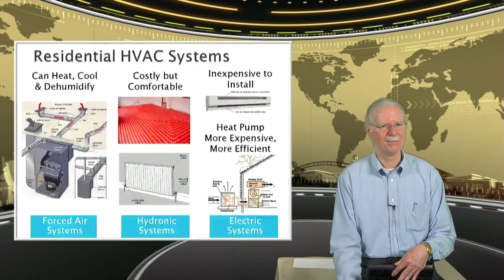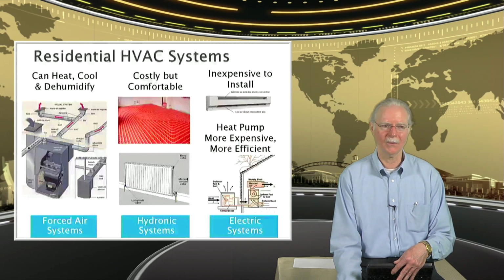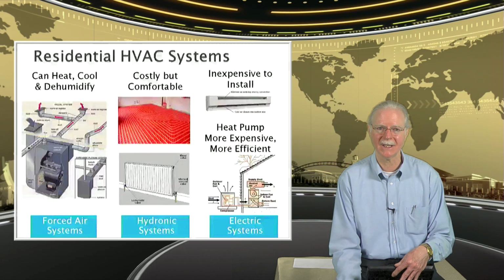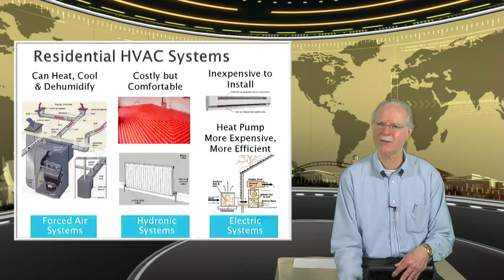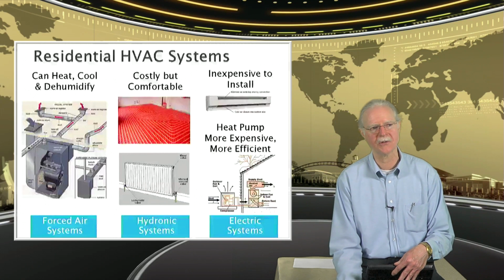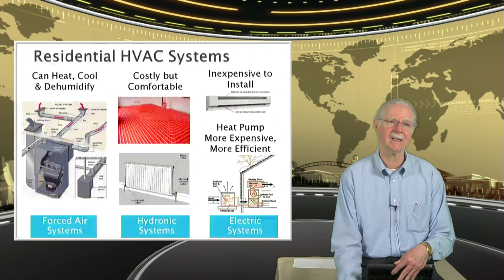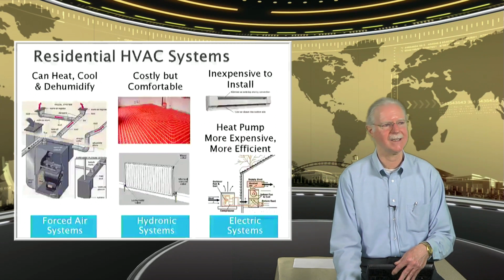Because we're now burning that fossil fuel right at the site, we have a pretty efficient delivery process. Natural gas comes to us at the residence at 100% of its value. It hasn't been degraded as it passed through the pipes. Fuel oil, same situation. Whether it arrives with a pipe or whether it arrives in a truck, it's got 100% of its potential. So what we're up against is how efficiently does the furnace itself capture the heat from the burning and pass it to the air.